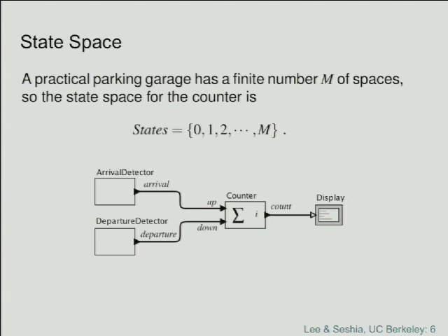Okay, so last time we were talking about state machine models, and I spent a good part of the lecture on characterizing the input and output of this garage counter. Just to remind you, what we settled on is that the inputs would be discrete events which occur in time. So time is modeled as the real numbers, and the input up is a function that maps the real numbers into either present or absent. We call such a function a pure function, where the value can only be either present or absent. That's what we mean by the term pure.